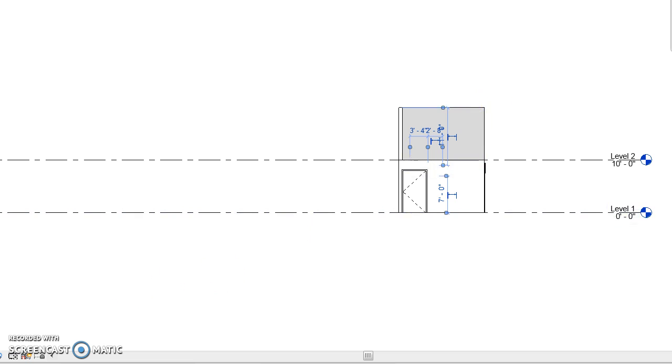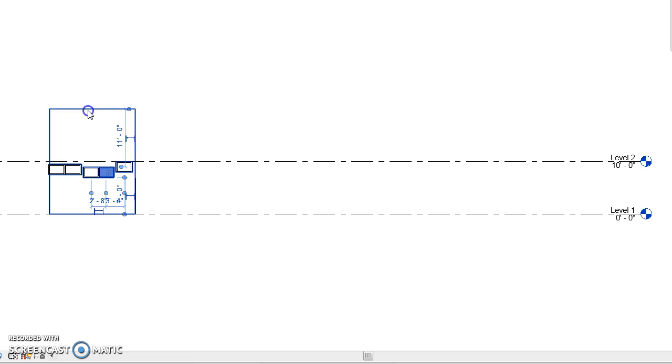Okay, so I've got my west view. Now I'm going to bring my ceiling all the way down to 10 feet. And then I can move my windows a little bit up higher. And do what I just did. And again, the easiest way to learn Revit is just to keep messing around with it. It's kind of like SketchUp from last year.